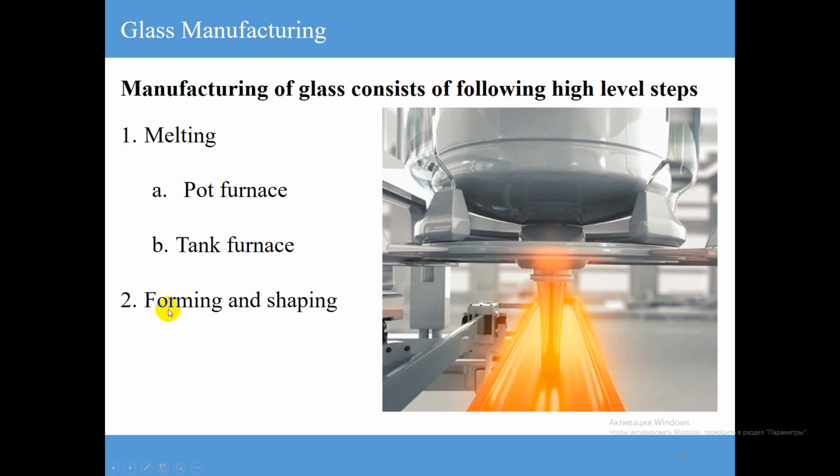Next step is forming and shaping. Glass from the furnace gently flows over the refractory spout onto the mirror-like surface of molten tin, starting at 1100 degrees Celsius and leaving the float bath as a solid ribbon at 600 degrees Celsius, and then coating for making reflective glasses.